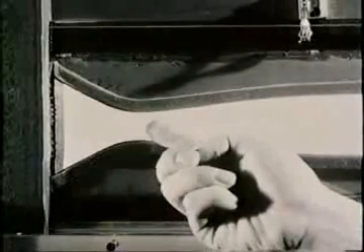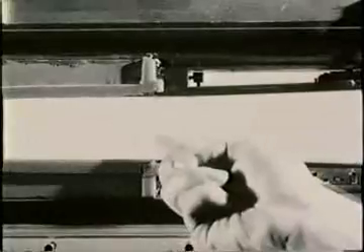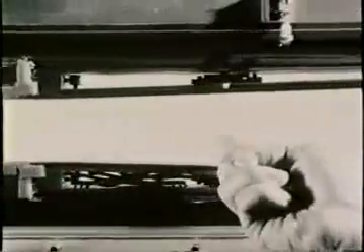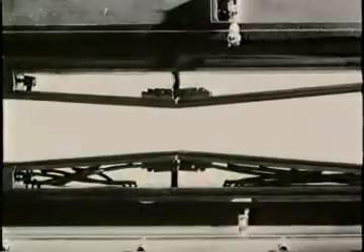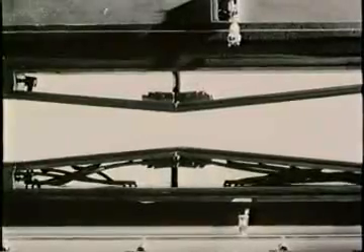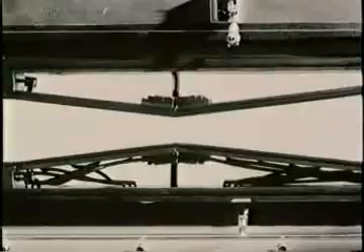Then we have an adjustable second throat, which can be opened or closed to vary the amount of supersonic compression. We now have two means of control over the flow in our channel: the geometry of the second throat and our original control valve. Let's begin by making the second throat smaller than the first one.